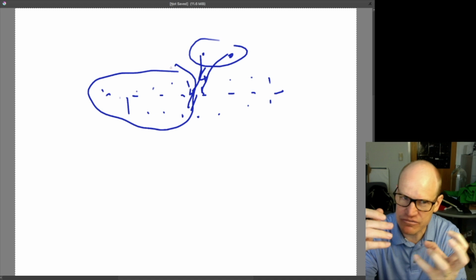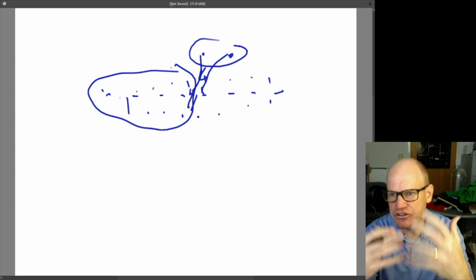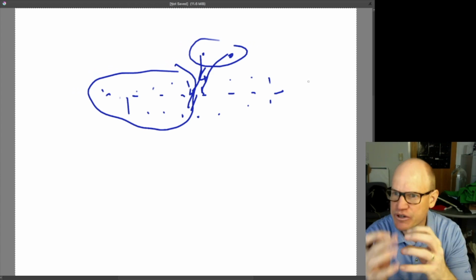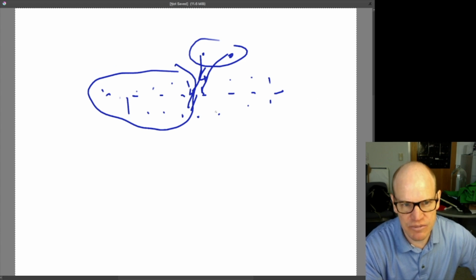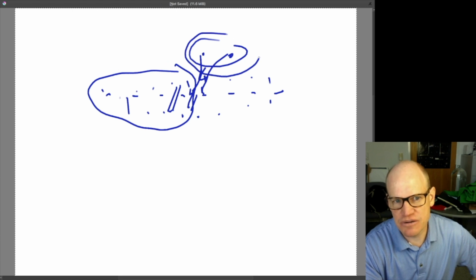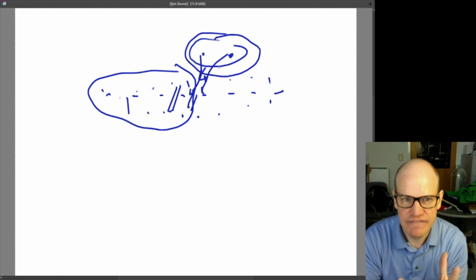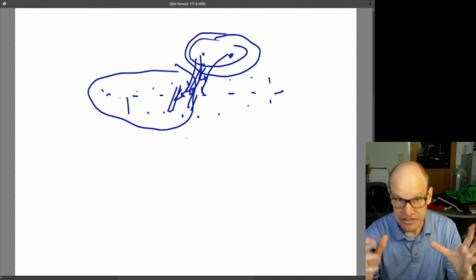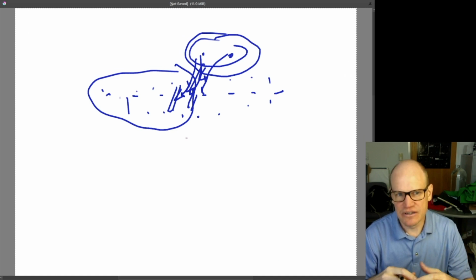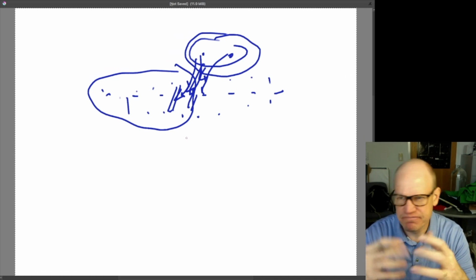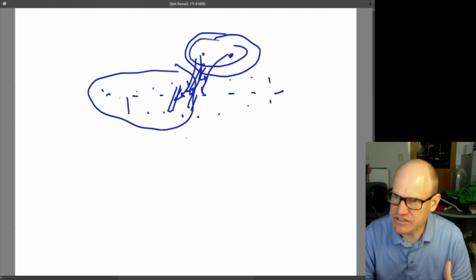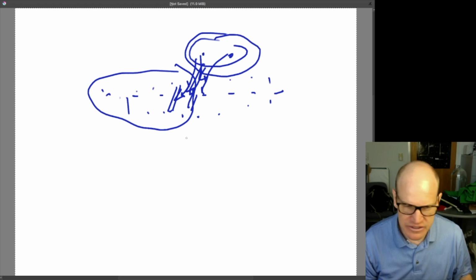You crack them by adding this hydrogen to it, but you have to have enough energy in there to break the initial carbon-carbon bond to begin with. So they have to be moving around fast enough so that when these molecules bump into each other, you break the carbon-carbon bonds. And then if there's some hydrogen in the vicinity that you can add to the mix, then those hydrogen atoms can bond in there and break it into different lengths. So that's a way of taking what you have from the crude oil and converting it into something else that might be more useful, to get a slightly different mix of byproducts from the distillation process or from the refining process.